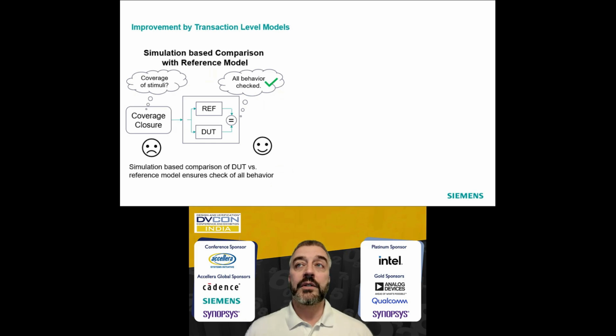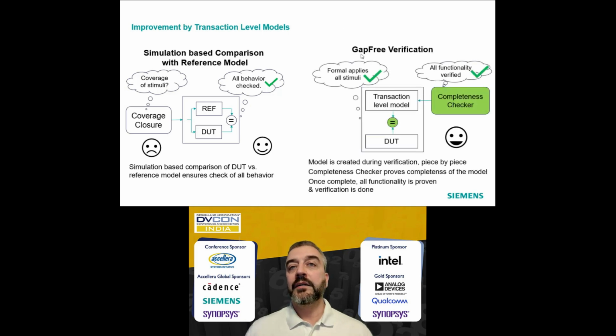Now, on top of these operational assertions or operational properties, there's also something very interesting I want to highlight, because essentially what you can get is also a way to run a one-spin gap-free verification, some kind of pattern technology that ensures that the set of assertions I've hinted at on the previous slide is really forming a model of the design. It really means forming a model in the strict sense of what a model is, meaning that there is no behavior in your RTL down there that is not explicitly modeled by one of your assertions.